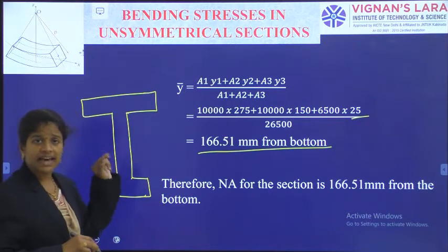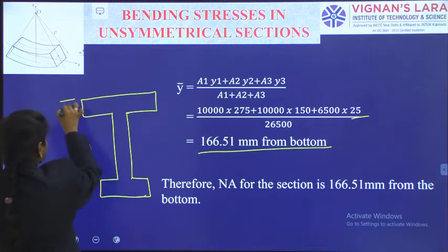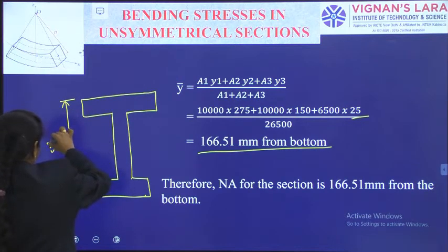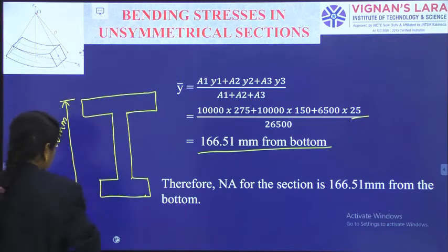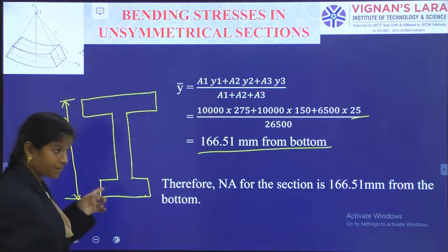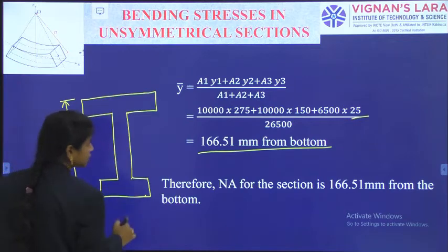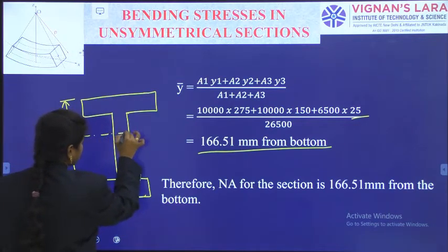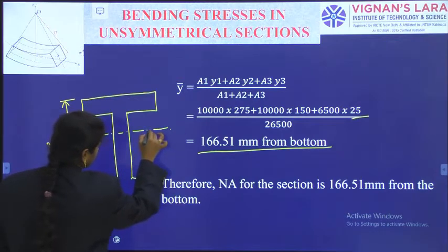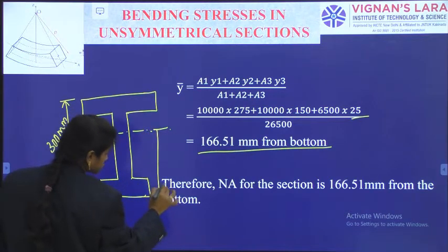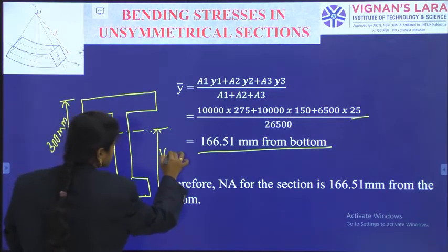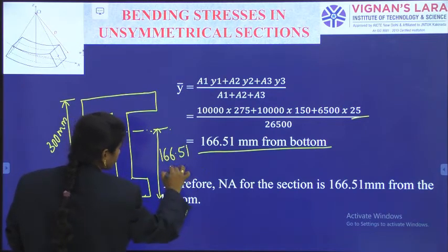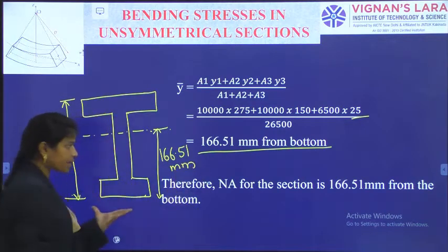It is having an overall depth of 300 mm, and in that the neutral axis is located at a distance of 166.51 millimeters from the bottom.